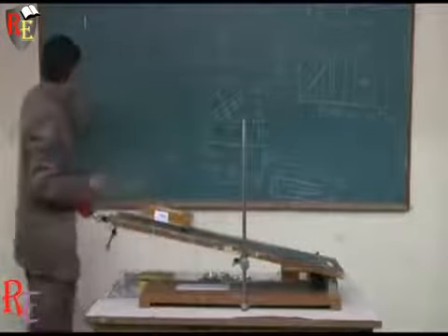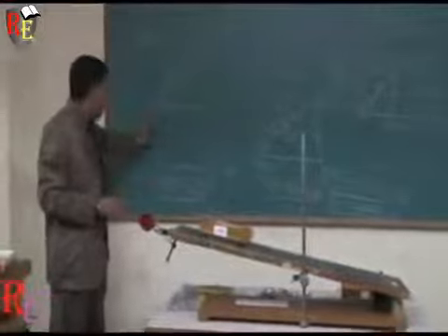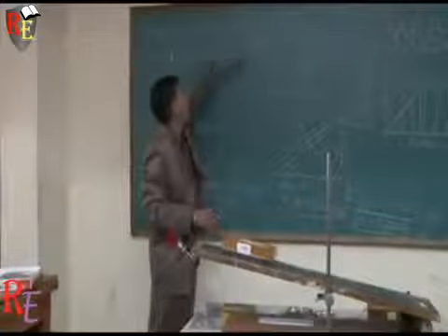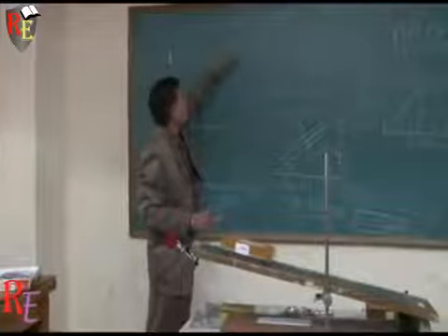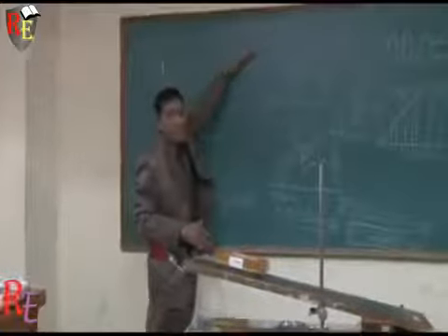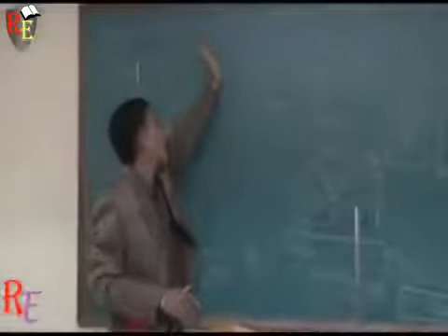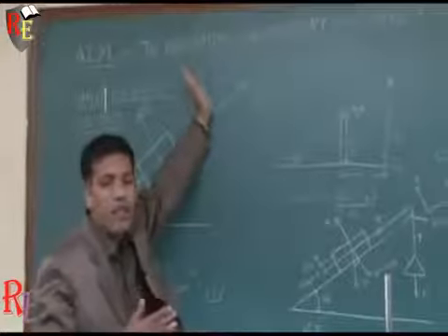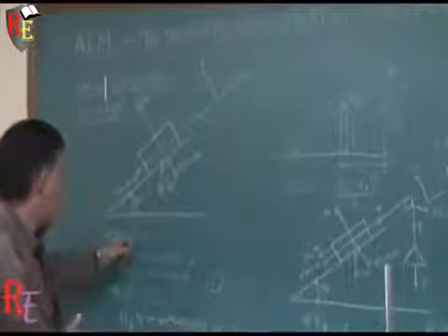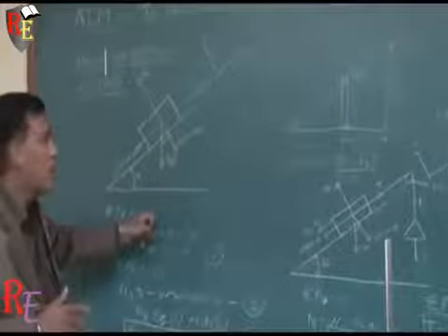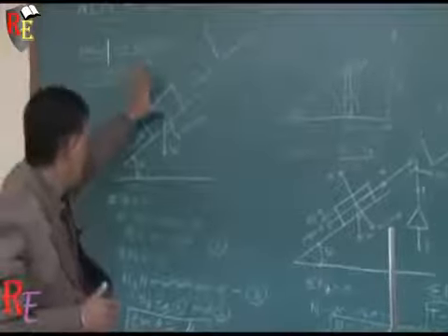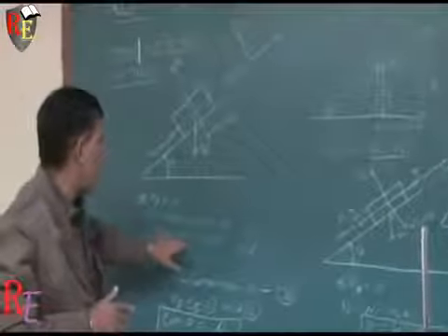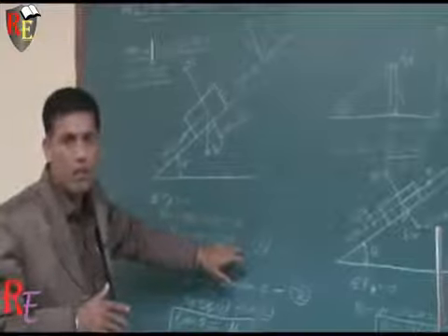So here I choose the x-axis as the direction along the plane, and the y direction as the direction normal to the plane. Okay. Now when I put sigma Fy equal to 0, then N minus W cos theta is equal to 0, then N comes out to be W cos theta.